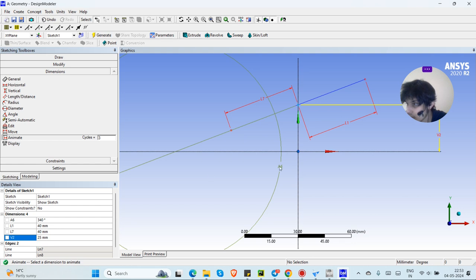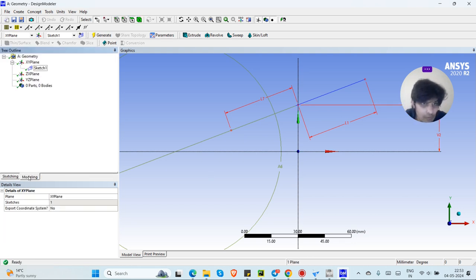Return to modeling using the tab. Okay, so right now we were doing sketching and now let's do modeling. Preparation, planning. So now we have the simple sketch representing the blade cross section. We will create the mixing blade assembly using a series of modeling operations using active bodies initially to create one unified body. Okay, where is my mouse pointer? Yeah, it's over here.